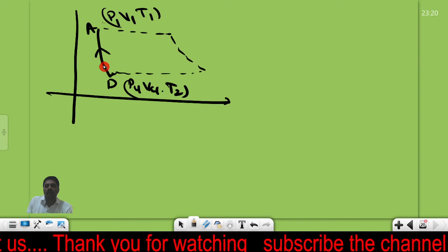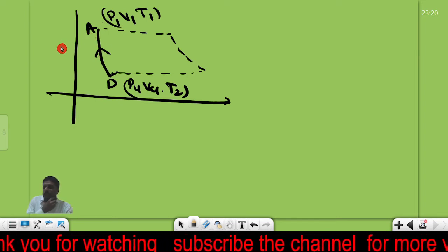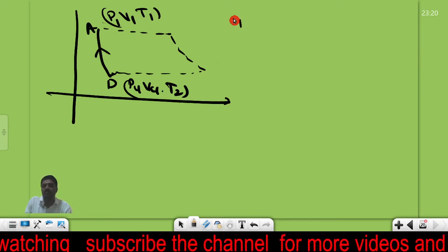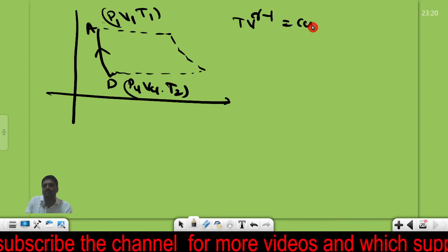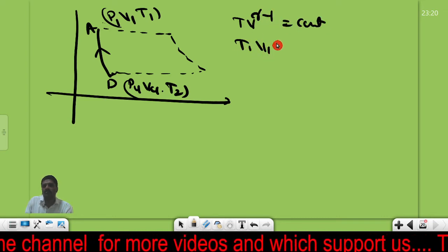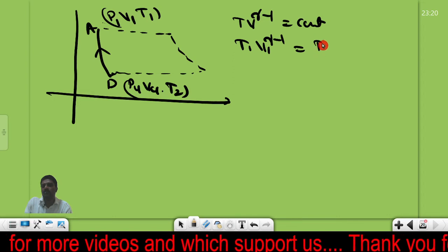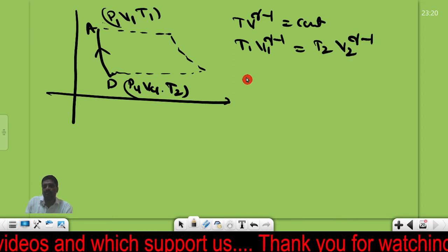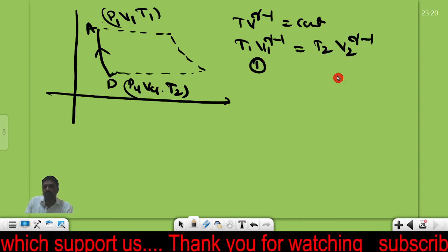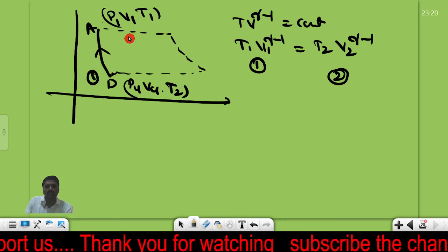Apply the adiabatic condition: T V to the power gamma minus 1 is equal to some constant, so T1 V1 to the power gamma minus 1 is equal to T2 V2 to the power gamma minus 1, for state 1 and state 2.